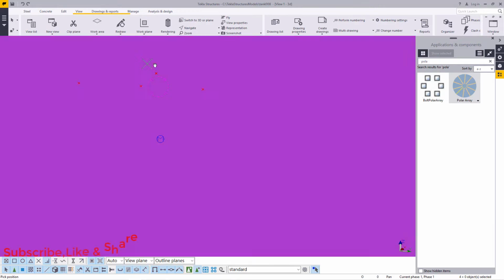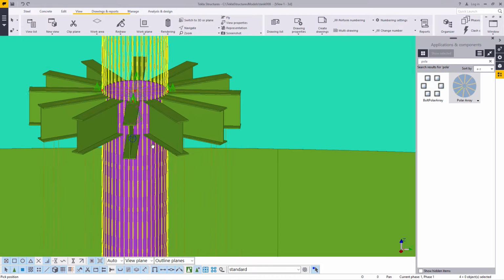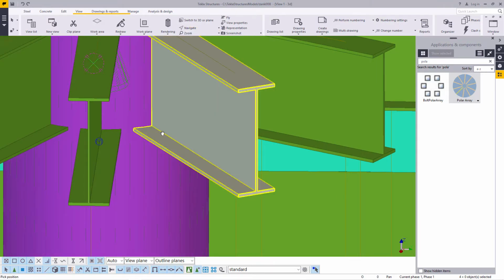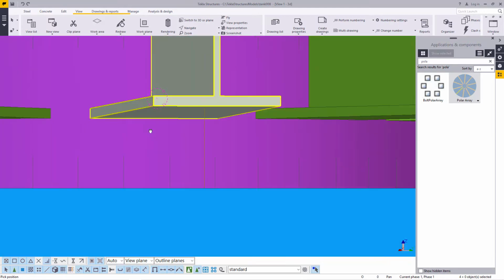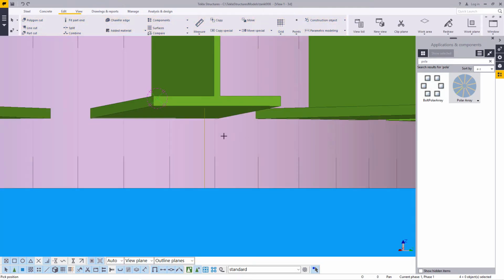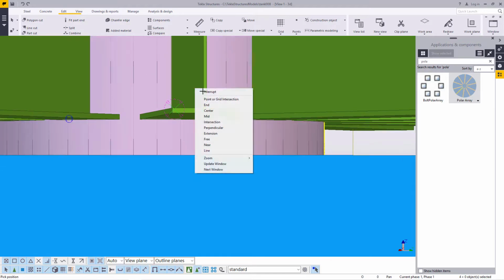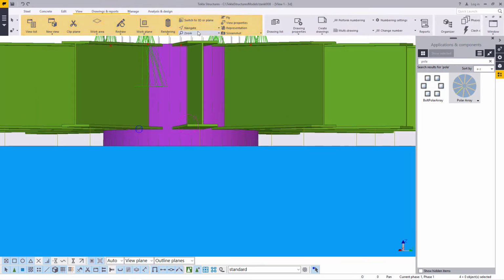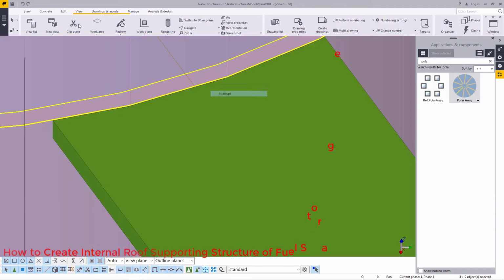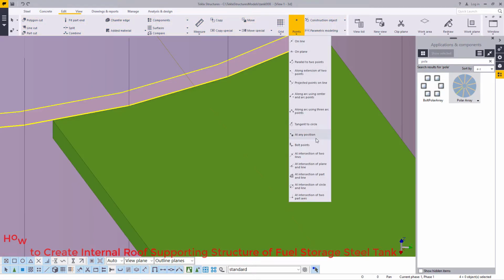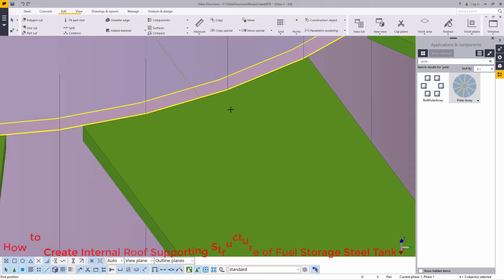So what I'm going to do, I'll first of all, let me just zoom in. You can't zoom in. Let me just bring this close and come to navigate, and I want to turn that around like that, and I want to snap right at the center, and I'll come to edit, come to at any position, and I'm targeting at the midpoint here. And to get that also, there's another way that will be easy to use without any obstruction from other components. I'll come to at any point, then I'll pick the midpoint here.